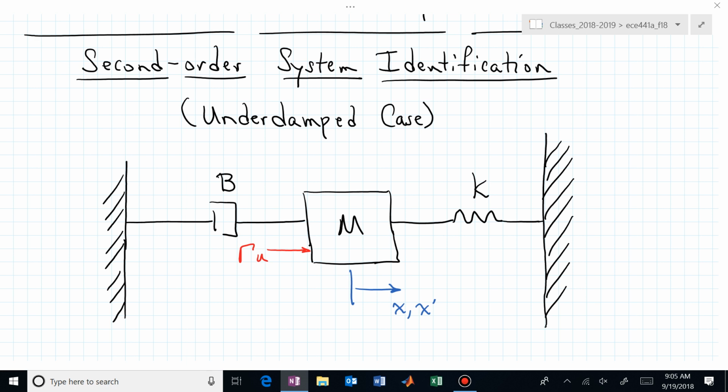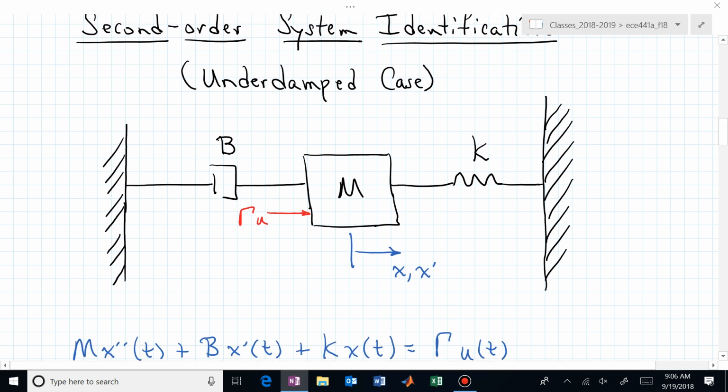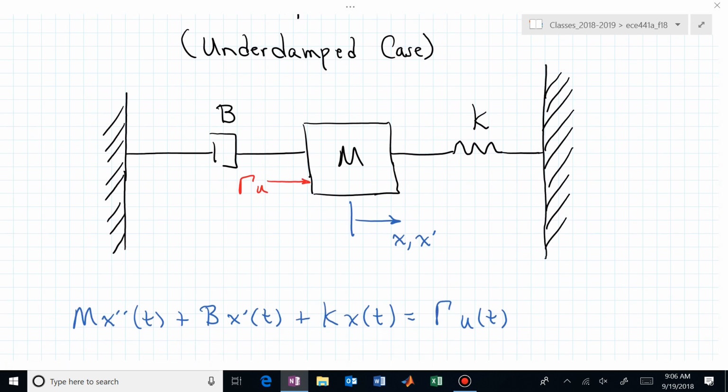That's a half a kilogram, and you need to account for that in your nominal mass. But maybe we don't have a way to measure the spring, although you might be able to put some apples on it and compress it a certain distance, and then you can get your spring constant of 400 newtons per meter or something, depending on how stiff that spring is, and your B. That's the damping, or it's now the coefficient that gives you the damping, and the damping is now proportional to the velocity of that moving mass M.